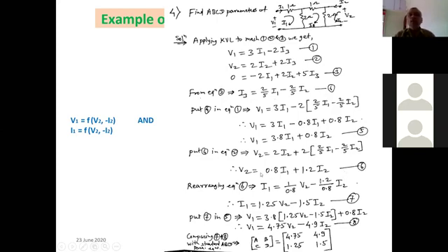Now, if you compare this 5 and 6 with the standard form of the ABCD parameter equations, this second equation has I1, V2 and I2, and this sixth equation also has the terms V2, I1 and I2. But the only difference is we want I1 on one side and V2 and I2 on another side. So rearrange equation number 6 so that you keep this 0.8 I1 term on one side and V2 and I2 terms on the other side.